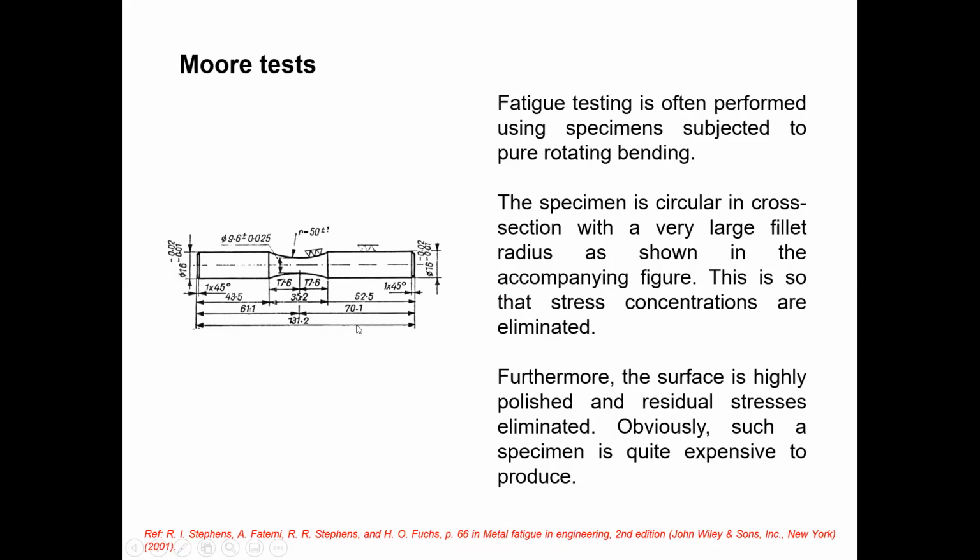This kind of specimen has special features. The surface of the sample, that is the specimen, should be mirror polished, and it's 8 millimeter diameter, standard size. And you can see these fillets are made smoothly. So this kind of specimen is very expensive when you produce it.